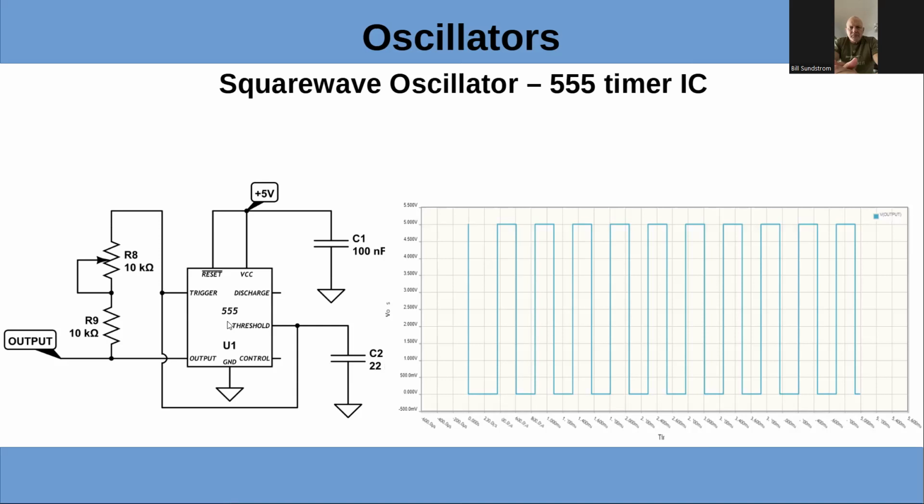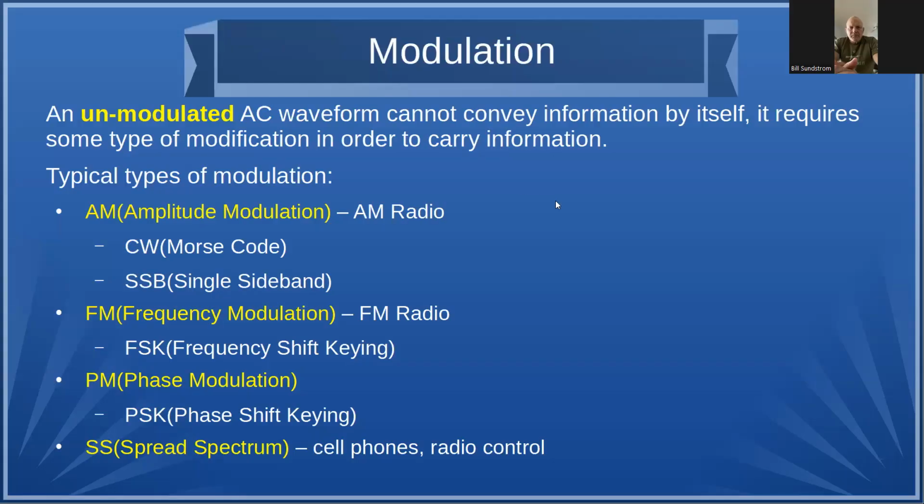It just takes one little 8-pin DIP. I was thinking it was smaller than that, but I think the 555 is 8. And they even have a dual one, the 556, I think. The 555 sets up switching frequency in the KG 102, a heading gyroscope.